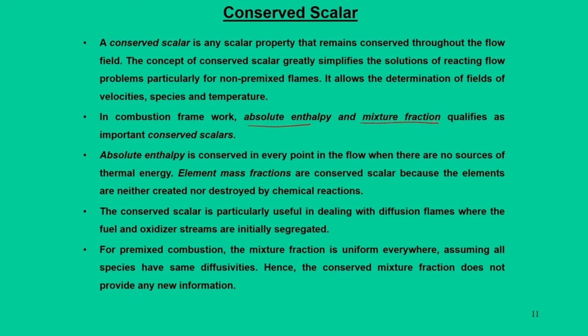In a combustion reaction many such conserved scalars are possible, but only absolute enthalpy and mixture fraction are very important conserved scalars. The concept is important mainly when we have a non-premixed flame. In a non-premixed flame, fuel and oxidizer species come separately, and not necessarily do they form a homogeneous mixture.